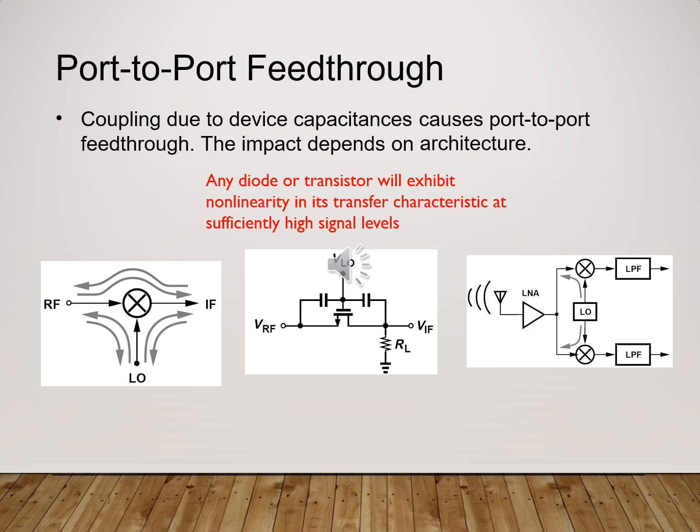Why measure isolation? Any unwanted signal leaking through the device will mix with the desired output signal, creating intermodulation products, adding to the intermodulation distortion from the nonlinearity. These unwanted signals may be difficult to filter out.